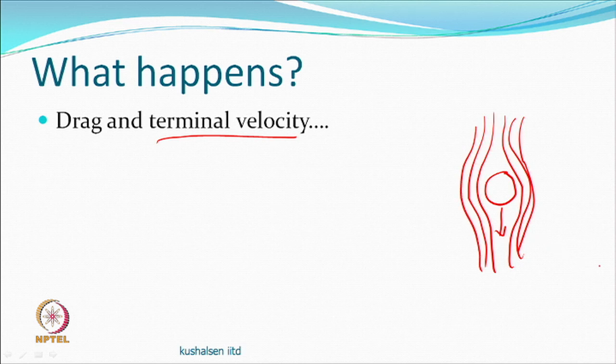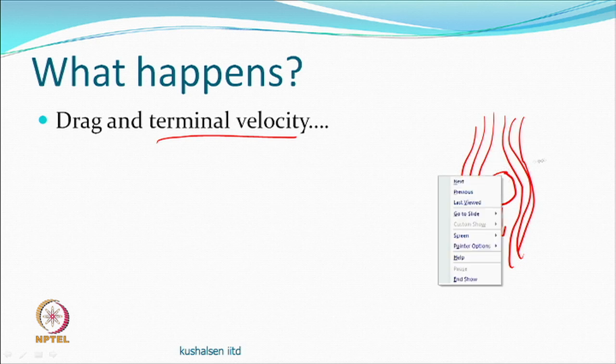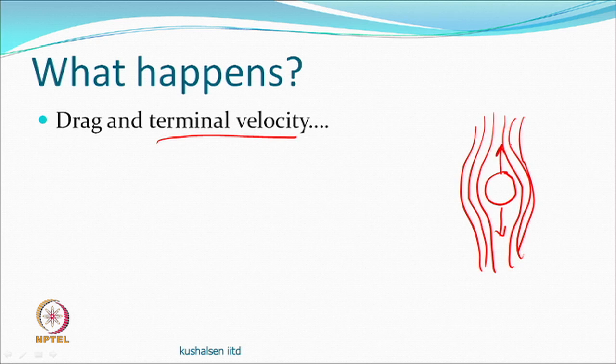Gravity is going to pull it down, but there is a drag force because of viscosity which will in some sense keep it up, and buoyancy, and this will depend on the mass, well, in fact, the volume and density, they are going to be related. So, if the density of the ball and the density of the fluid are the same, what will happen? It will just stay wherever it is. It will not change any position.